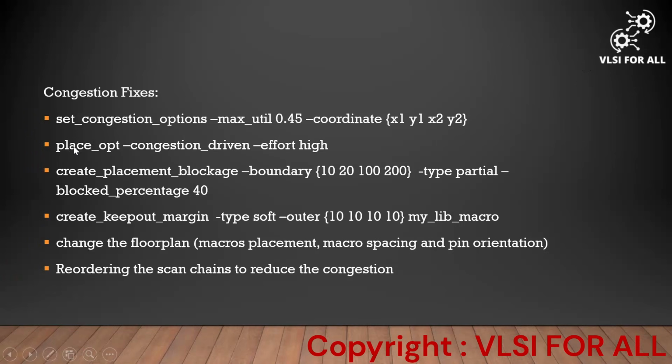The other one is place_opt -congestion_driven_effort high. We have to make sure the congestion driven effort is high, then only the congestion count will be very low. This is one of the techniques. Another technique is to provide blockages to reduce the congestion. We generally have three types of blockages: soft, hard, and partial. Based on the requirement of the design, to resolve the congestion, we use them accordingly.